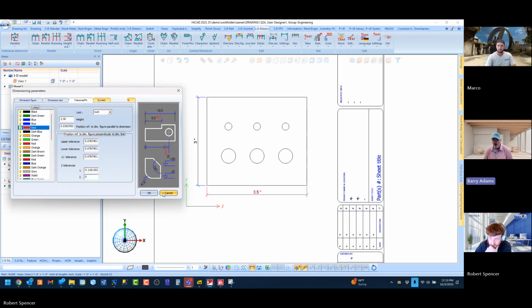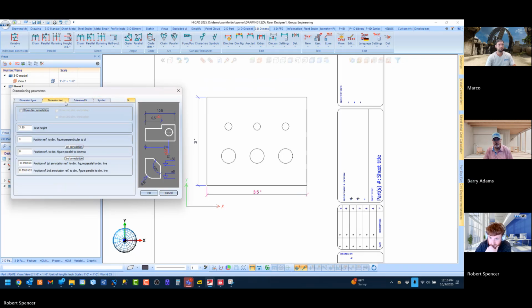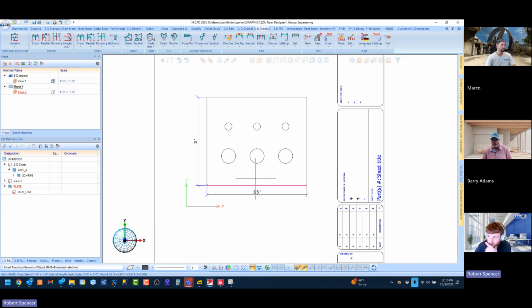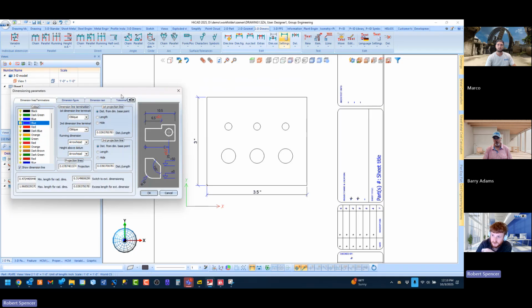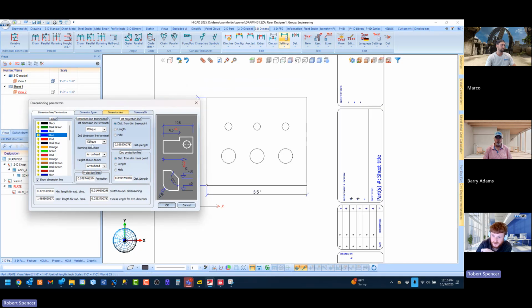This is like dim style in AutoCAD. Yeah, that's basically it. So now, if you want to set it globally for any dimensions moving forward, dimensions to be created from here on out, you click the very similar looking dimension settings here, which is the identical menu, but now what you do applies globally moving forward. It's not going to change what you've already made. It's going to change new dimensions to be created from this point on.